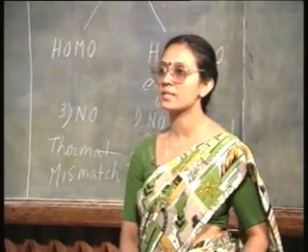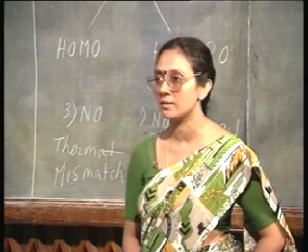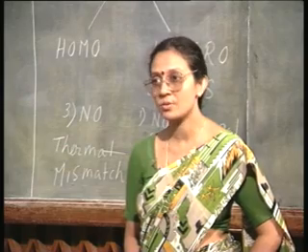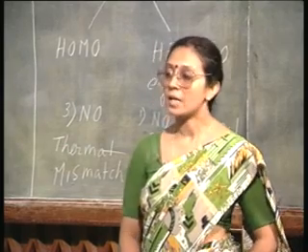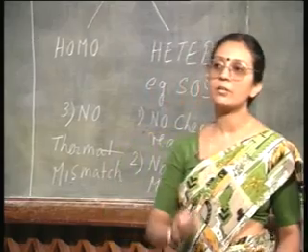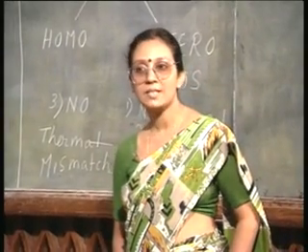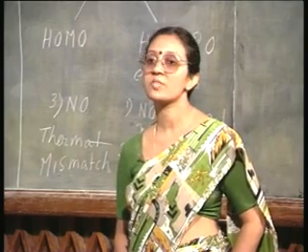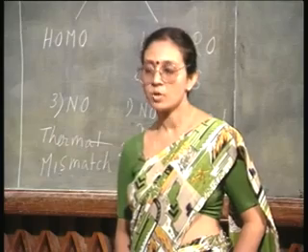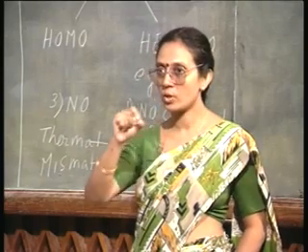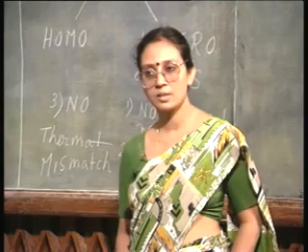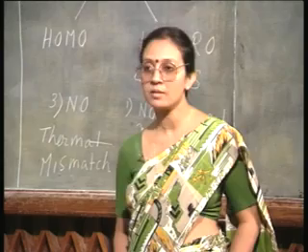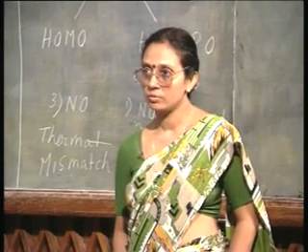I told you already that sapphire and silicon, there is no lattice matching. Sapphire is a hexagonal crystal, silicon is a diamond like crystal, there is no lattice matching, but it can be grown. The thickness of the layer, that is the problem. When there is a lattice mismatch, what will happen? There will be a lot of strain in the epitaxial layer. So, up to a certain thickness, if you are growing very thin layers, this strain can be tolerated. Beyond that, it is not allowed.